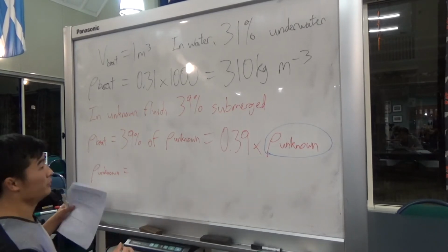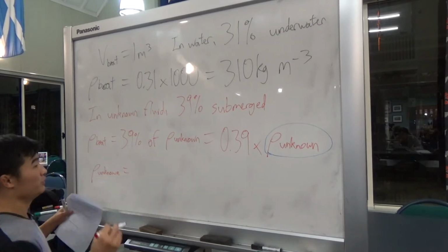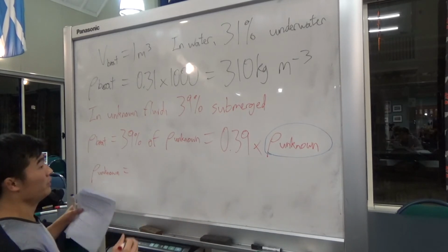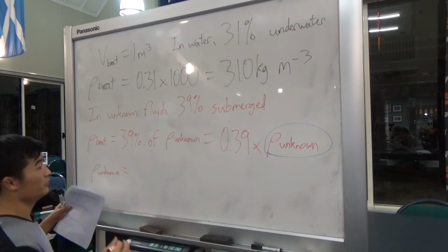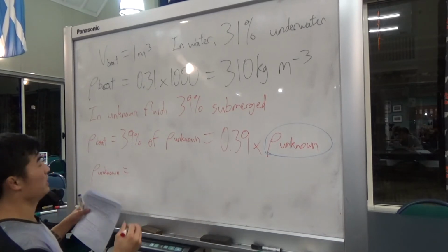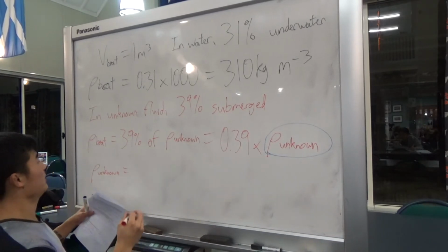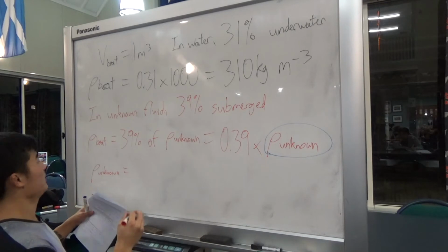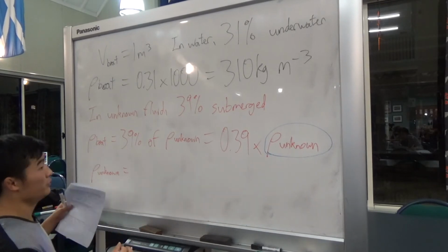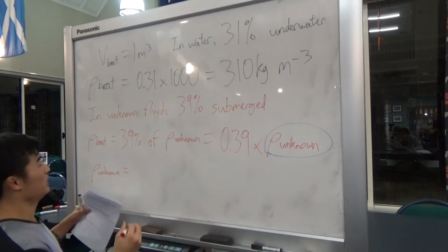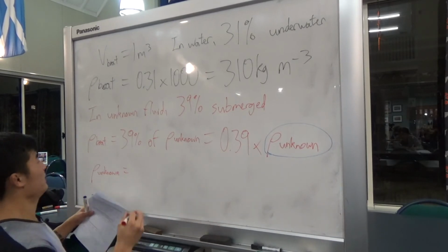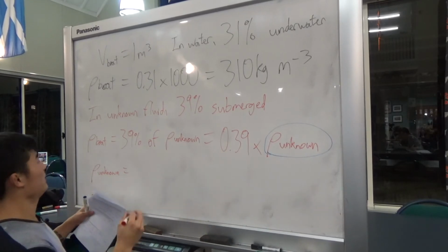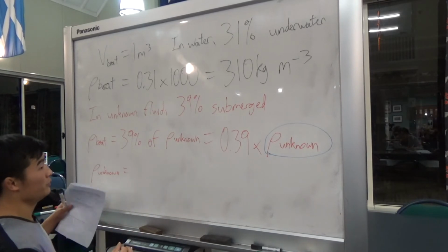And now question number 9, so we're continuing on from that. What's the difference in pressure between section 2 and section 1? So you're going to use that long equation. So P1 plus rho GH1 plus half rho V1 squared is equal to P2 plus rho GH2 plus half rho V2 squared.